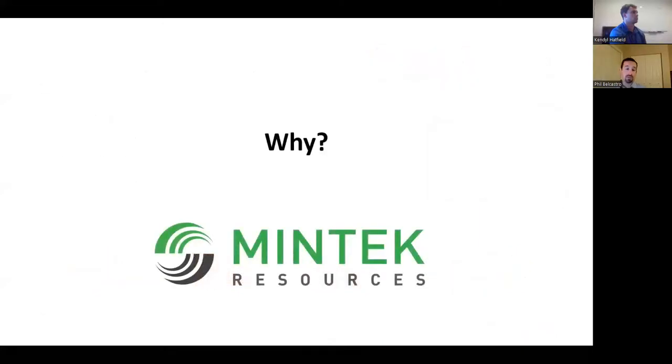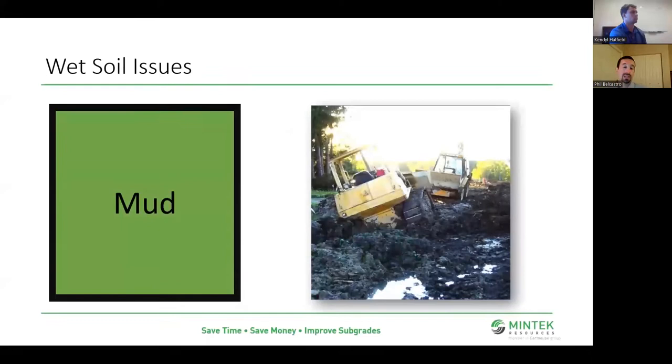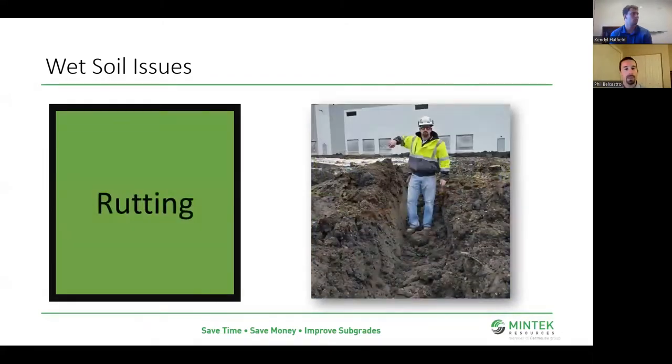But why do we want to use these products? So anytime we've got our crews out there stuck in the mud, not getting any work done, no productivity, I want you to think about lime. Want to improve some of those engineering properties once again. Maybe we're having some rutting issues on the site. Here's a picture of me pre-COVID days out in Chicago. We were getting some benefits of soil modification, but we're really just trying to dry the soil with the quicklime.